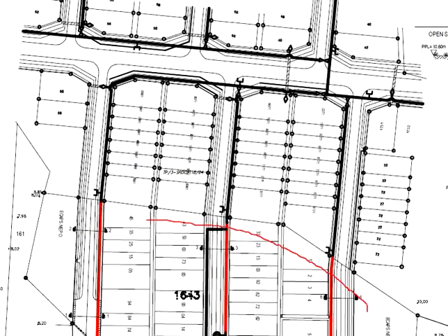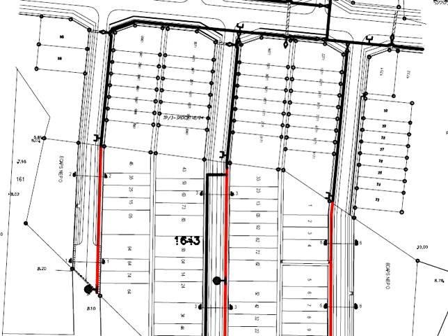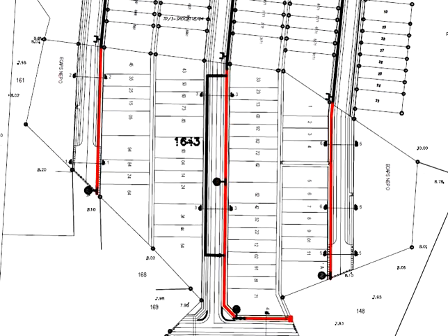Normally, before we propose the water reticulation system, we need to have an idea of the existing main systems in order to determine where the intakes of the water are, where to tie in the proposed mains so that the water can reach the developed areas.